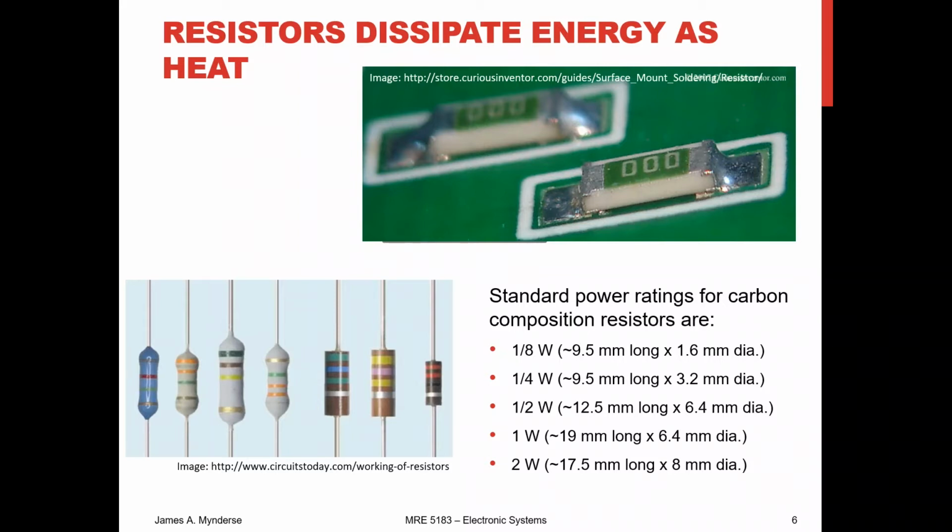If you buy a kit, it may very well be 1/8 watt. And then when we're dealing with components like large capacitors, where we want to dissipate the energy, we may need a much larger resistor. Or if we're dealing with simply larger power systems, we might need a much larger resistor.